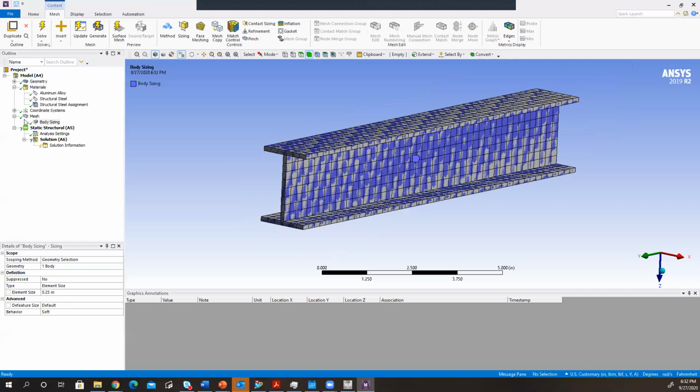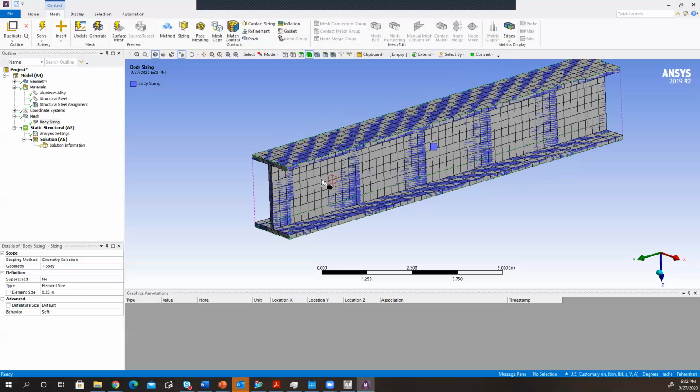Okay, so for this particular geometry, the mesh checks out. But like I said, if it's anything more complex and you ever want to fix it, you need to do several things. Sometimes if you have anything that's rounded off, like a fillet or some geometry that has a radius, instead of making uniform square rectangle mesh shapes, it's gonna do some sort of triangles or polygons. That's good if you're doing rounded objects, but sometimes that's gonna give you some inaccurate results.